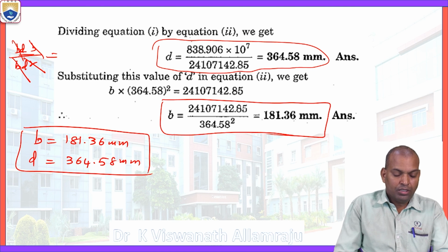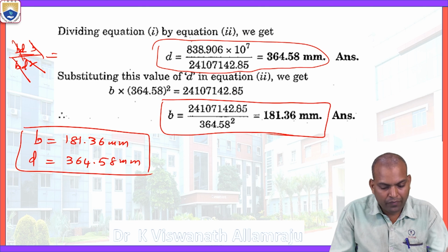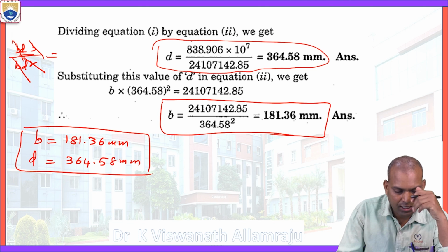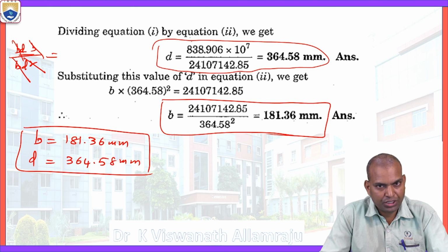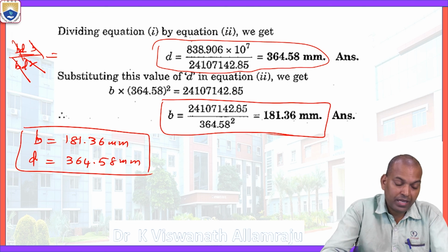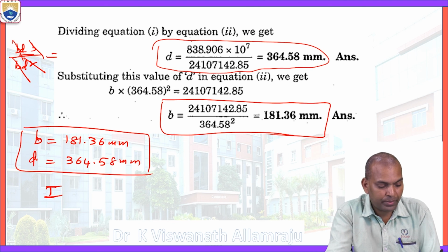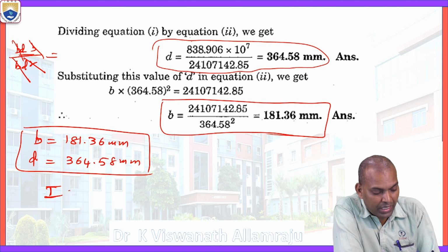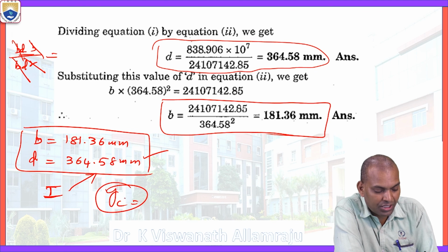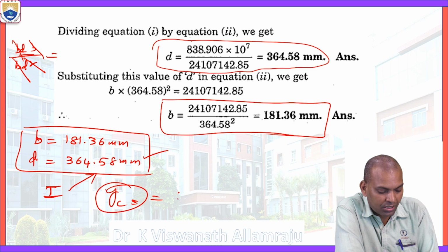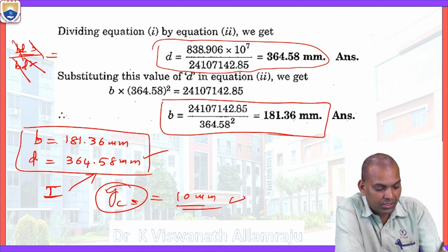Alright. So the novelty of this problem is that the maximum deflection was given. The cross section of the beam gives the value of I, the moment of inertia, the second moment of area. With this geometry and the moment of inertia calculated, the deflection can be known. If we substitute these values, 10 millimeters will be obtained.